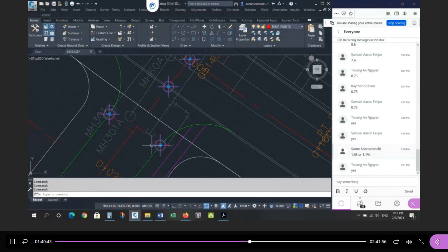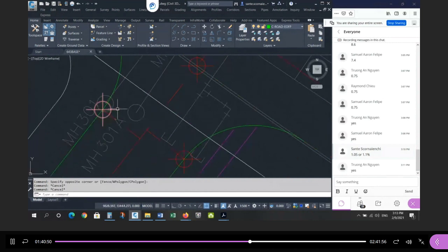Here's the 2 points at the end of the curve here and the end of the curve here. We're only going to use one of them, but I'll project both. Here it's obvious. You can see that this one's further back, but I'll project both. And you'll see it in the profile. Whichever one is further back, that's your low point.